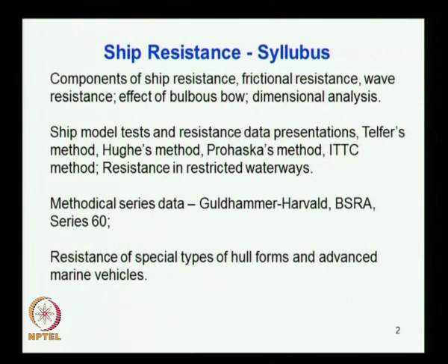you have variation in resistance when the ship moves from deep water to shallow water, and that too if the restrictions are more in the breadthwise direction, that is, the case where the ship moves into a canal or a river, where you have additional restrictions from the breadthwise direction of the waterway.